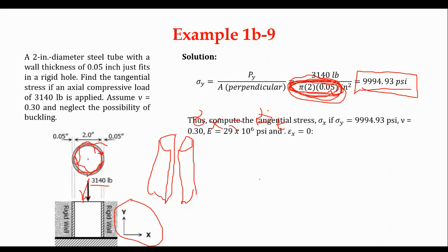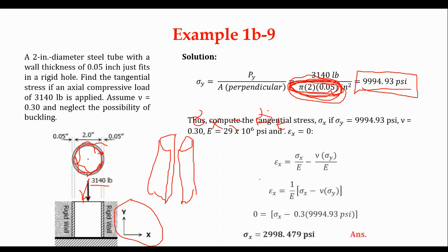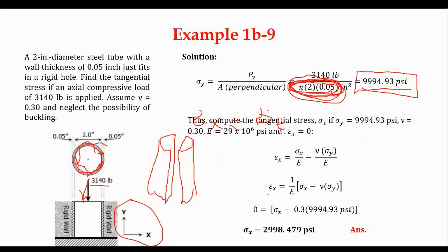Okay, so, to solve for the sigma x, given na naa na tay sigma y, kanina, relationship. Diba? Strain in x is equal to the stress in x over E. Then, apil pod ang stress in y over E. Para ma-convert, you need to multiply the Poisson's ratio. So, substitute, okay.